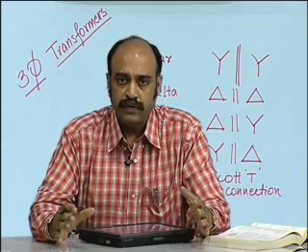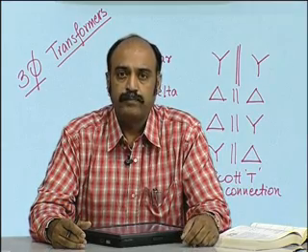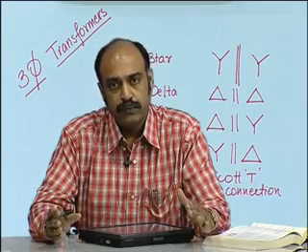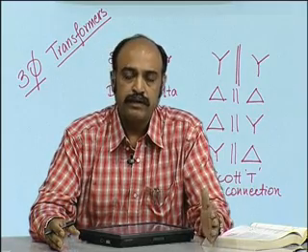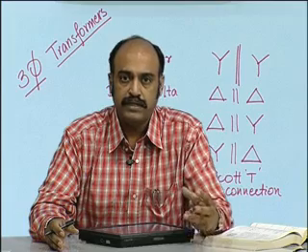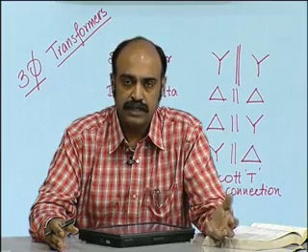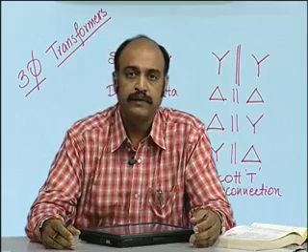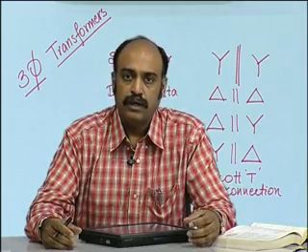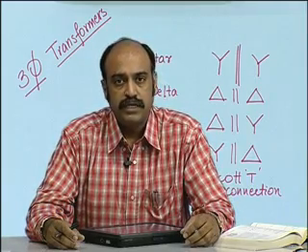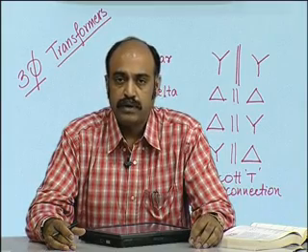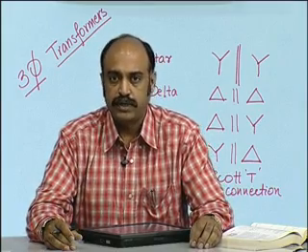So, these 4 configurations we studied, had a look at the various relationships between the phase and the line side parameters of the primary and the secondary side, and we also were able to study the phasor diagram for these 4 types of three-phase transformers.